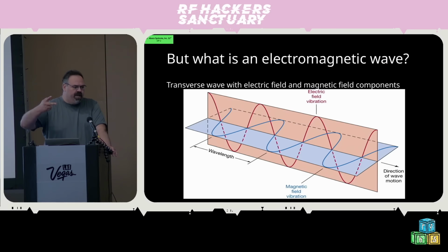You end up with 2 components of this wave. There's an electric field, and perpendicular to that is a magnetic field. You can actually set up antennas that are specifically designed to pick up what is called the H field or magnetic field, which is kind of cool for some frequencies that tend to be very noisy, as the magnetic portion of it tends to have less local noise generated. So if you have like an HF listening station, then use a magnetic antenna, and it doesn't sound quite as terrible. Anyway.